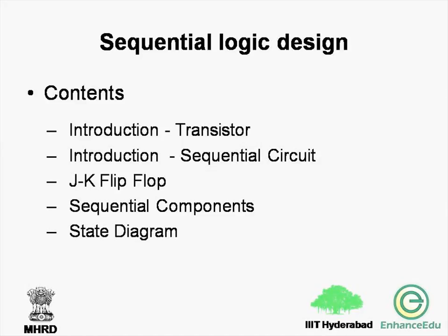A sequential circuit, which is a digital circuit, gives outputs that are a function of the values of the current as well as the previous inputs. Elementary sequential circuits include the flip-flops, commonly known as D flip-flop, SR flip-flop, and JK flip-flop. The other sequential circuits are registers and counters.